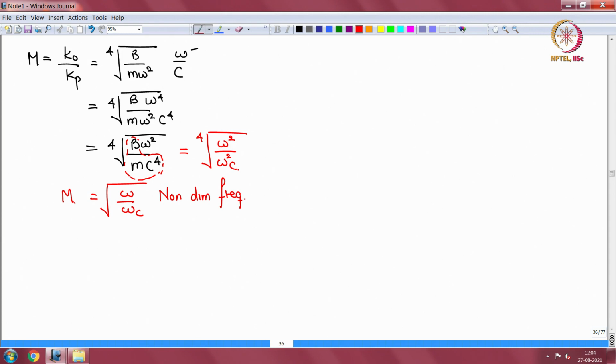The other material non-dimensional parameter, epsilon, let me write it, is rho, the fluid density, times the speed of sound, divided by the mass per unit area of the panel times the coincidence frequency. This is the other parameter. So these are the two we need. There is a discussion behind it and so forth, but these are the two we need.